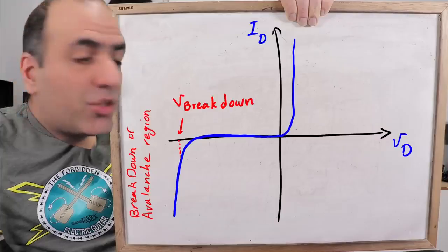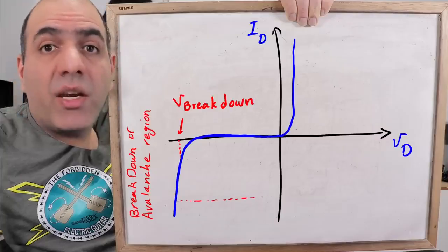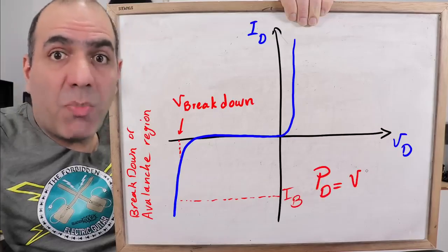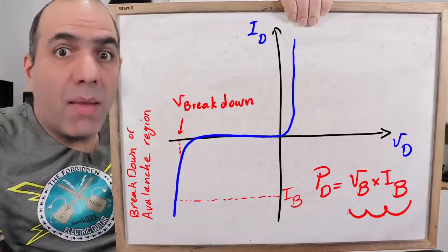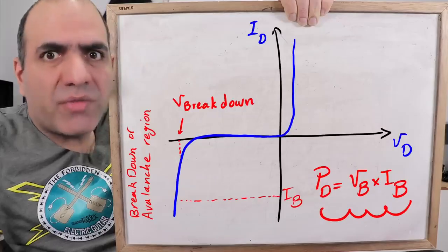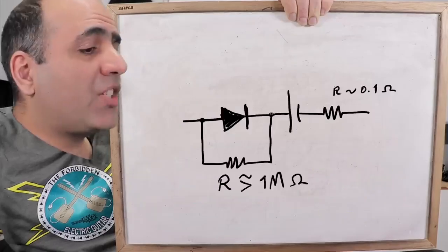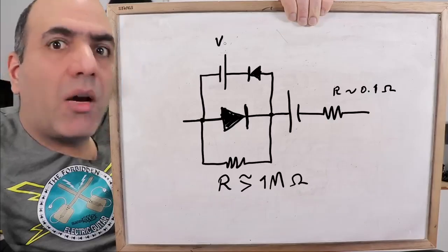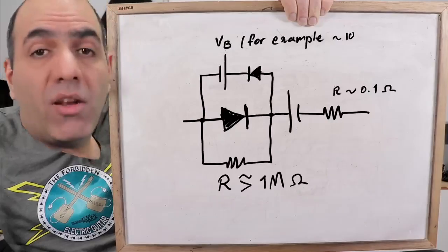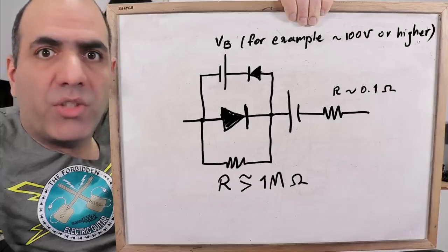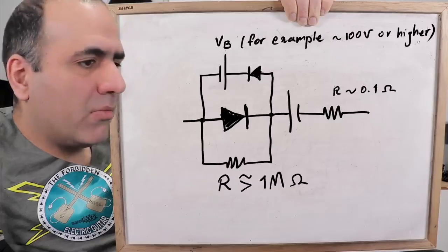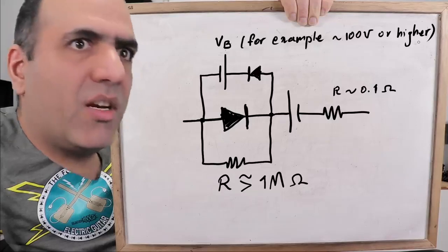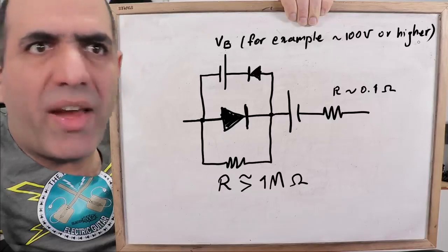The reason the diode dies here is because you would have very large reverse voltage and current through it, which results in very large power dissipation. It heats up quickly and blows up, unless you get out of that region very quickly. That can be modeled with a reverse ideal diode and a battery with the breakdown voltage value. You have to be larger in reverse than this voltage for the diode to conduct backwards. We typically ignore this because we keep below that voltage level, because that's not a desirable effect.